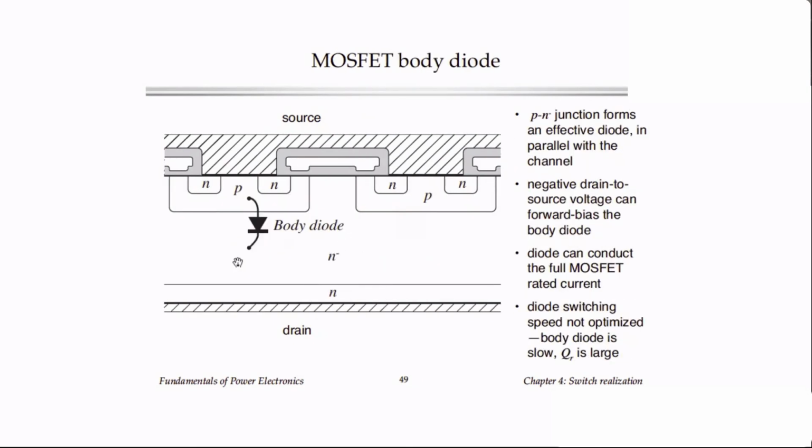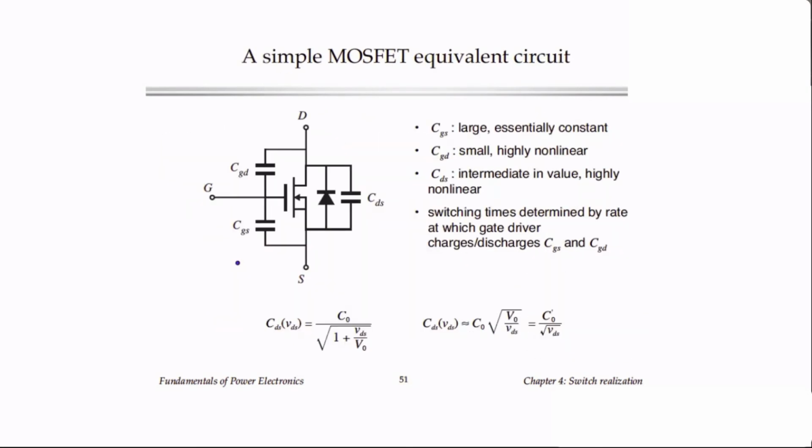It's non-linear. We didn't talk about this with respect to the PN junction diode, but it's actually a similar kind of function. Here's a classic formula for a depletion capacitance, and it's a nonlinear device where the capacitance varies roughly as the inverse square root of the voltage. So as the voltage goes up, the incremental capacitance goes down, and we get this inverse square root formula.